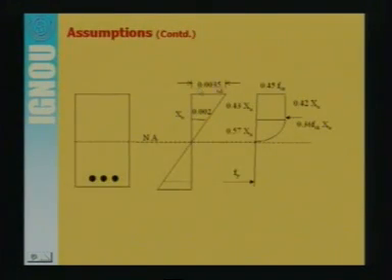Now, we see from here, this is the strain in the outermost fiber in compression zone. This is the section of the beam, this is strain diagram for this section, and this is the stress diagram for concrete for the given section here. So, we calculated that the design strength here for concrete comes out to 0.45 fck. Now, as you know, this is the neutral axis. So, we are interested in knowing what is the shape of this stress diagram, where some important values lie.